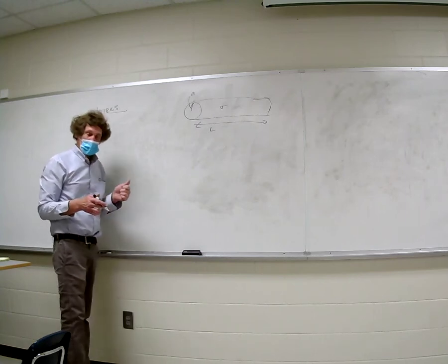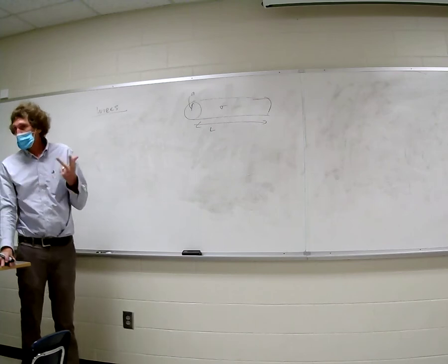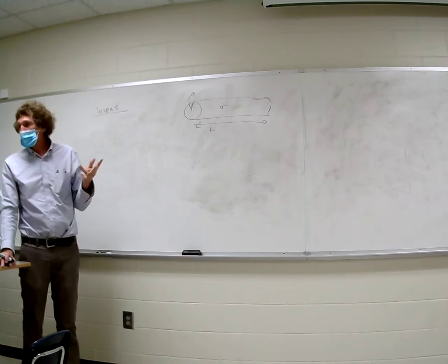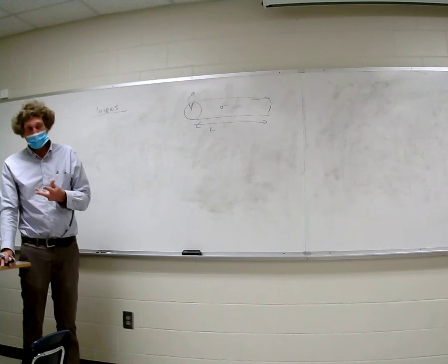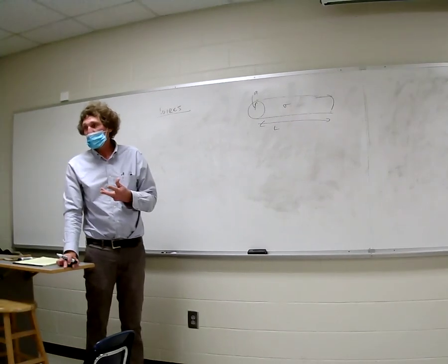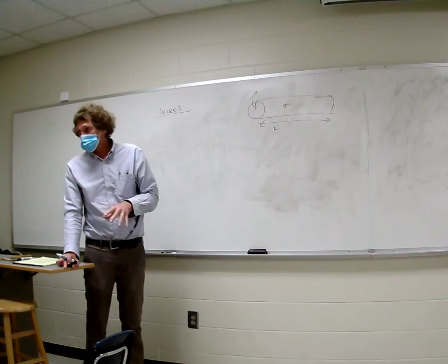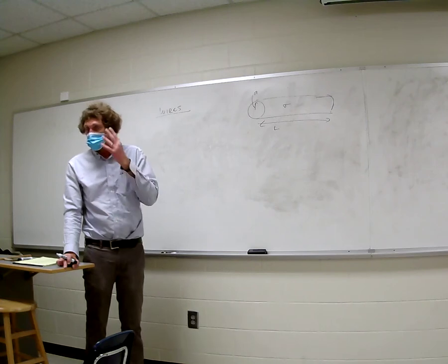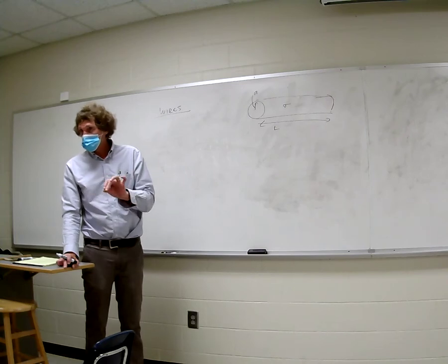And if you think about it, gold, silver, copper are the three that you think of right off the bat. Aluminum is also a good conductor, not as good as copper. But there's one other thing, it's steel. Now, steel has a conductivity about 1/10 that of copper, but its relative permeability, mu relative, for 1050 steel, is about 1,000. So that factors into a big change in the self-inductance. And these are things you just have to keep in the back of your mind when you're doing any type of engineering that involves stainless steel or steel generally.